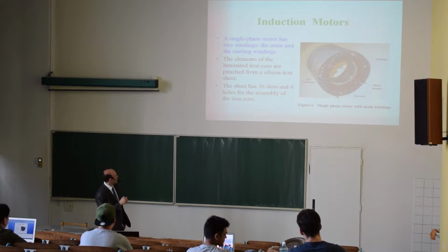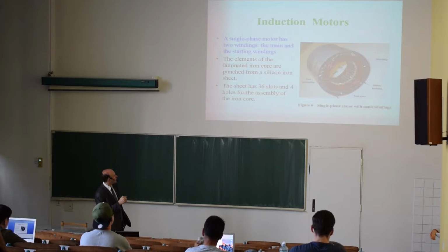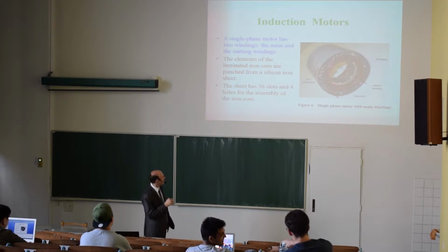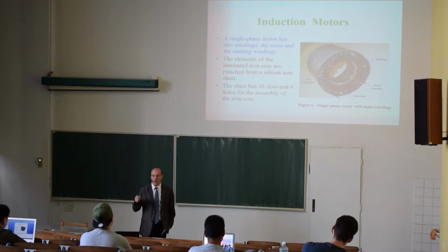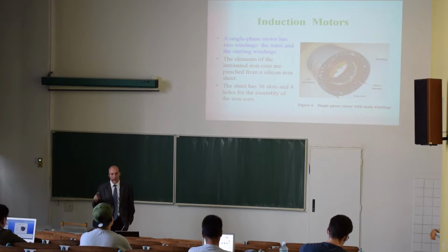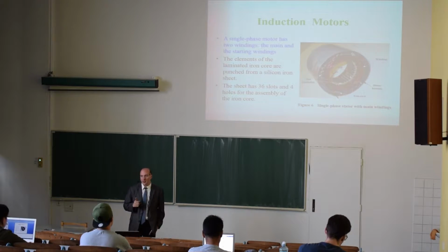The number of slots that you have is given by the construction, by requirements for speed. So this specifies what speed the motor should have, and as we will see, I think next week, the speed of the induction motor is a function of frequency.